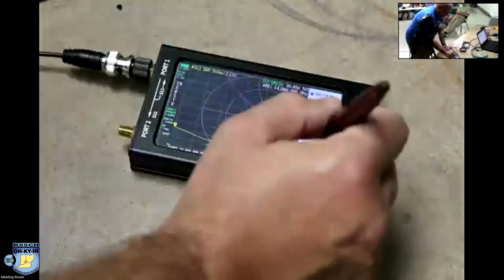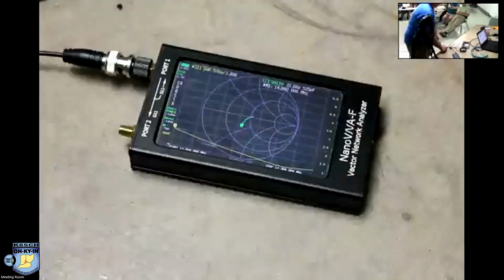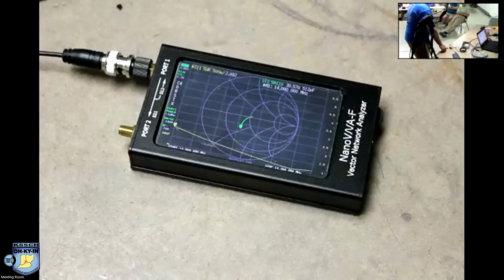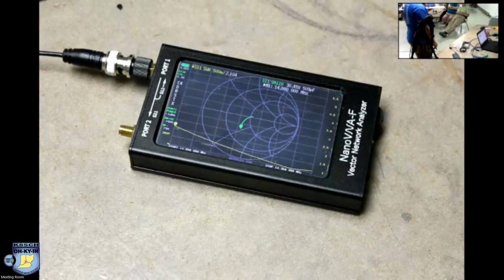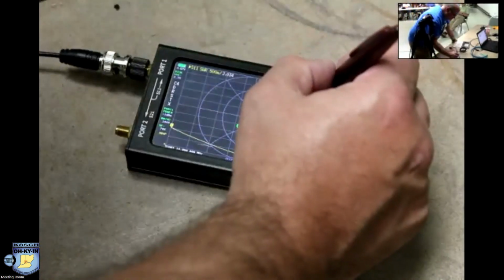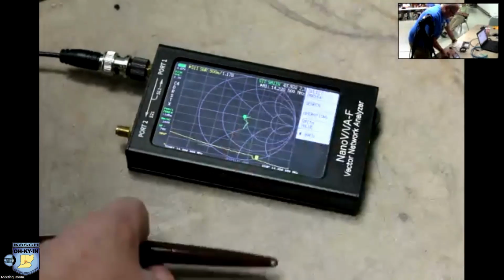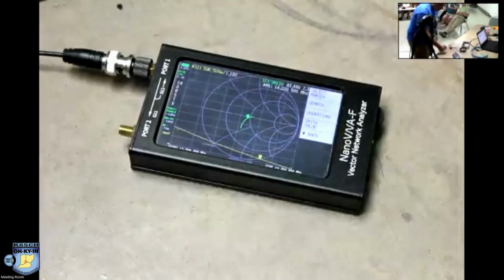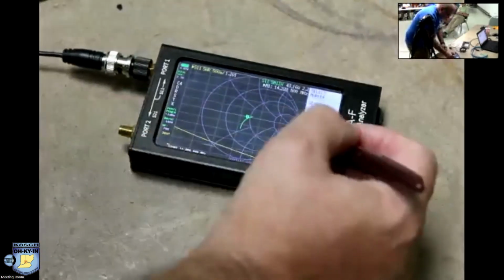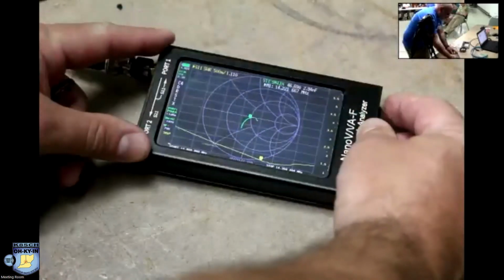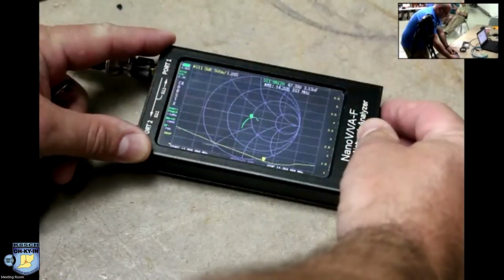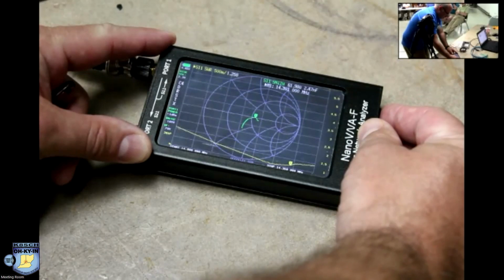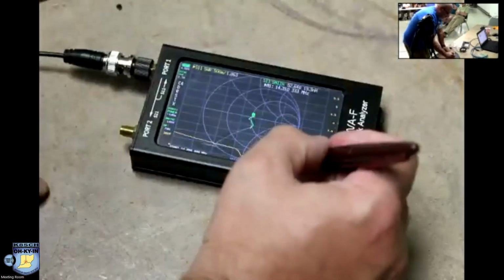It's kind of hard to see right there. If you ever try using log mag, you can see that sometimes a lot better. Yeah, I've done the log mag before but it's usually for measuring inductance and capacitance. You can see where the SWR is also on log mag. Well, you can also do the minimum there, and it tells me that, again, I'm also in the near field here. The minimum is 14.22. You can also use the rocker switch. I don't know if you can see that little yellow guy moving around on the end. Yeah, it also allows you to.